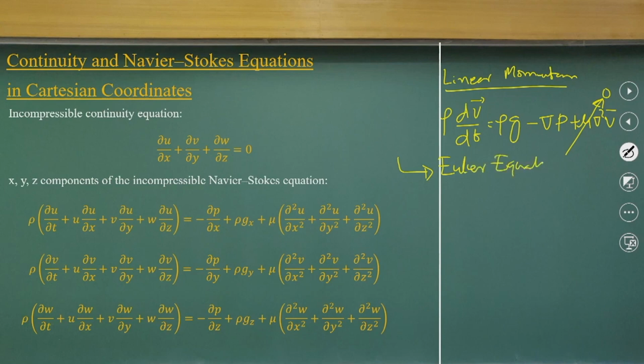That means we have rho dv by dt equal to rho g, and we are still using these vector operators, del into phi. So, these are the regions where the viscosity does not dominate. In those regions we can apply the Euler equations, which have only two force components, the gravity force and the pressure force, balancing mass into acceleration. That is the basic equation we have.